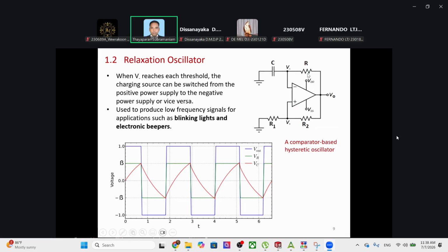But there's another issue popping up: what if the supply voltage is not sufficient? We have to carefully decide the supply voltage of this op-amp so that the effect of the diode drop is minimized. Otherwise, if it is 2 volts and the diode drop is 0.7, it is going to have a serious effect on the performance. But again, you can design it.